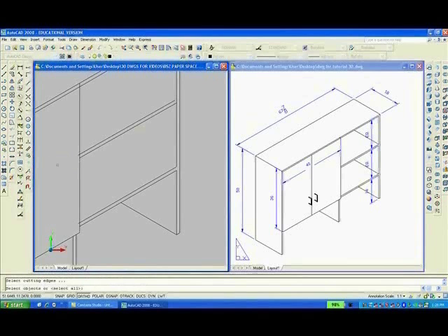Going to trim from this line into that little bit, and we're going to break and fillet it. Clean up these two intersections. And we're going to trim, TR, enter, from this line into that one,